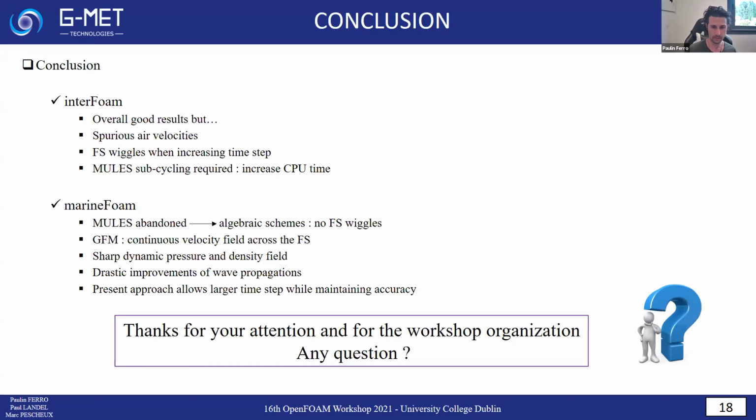We observe that when you use the ghost fluid method, the ventilation is diminished. So we have less ventilation with the ghost fluid method than with the traditional mixture formulation. This is a very large improvement and has a lot of benefits for the solver.